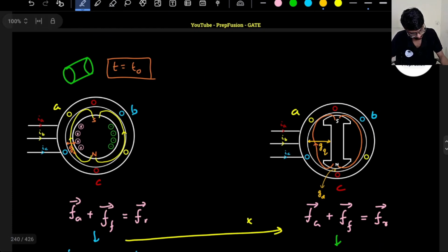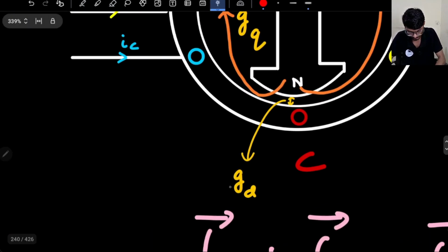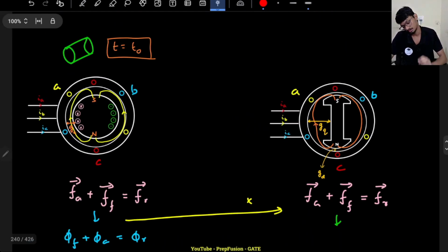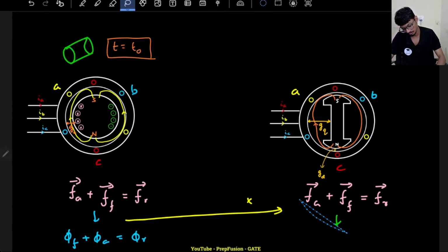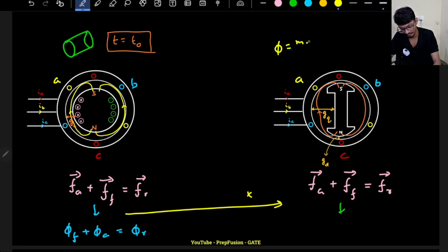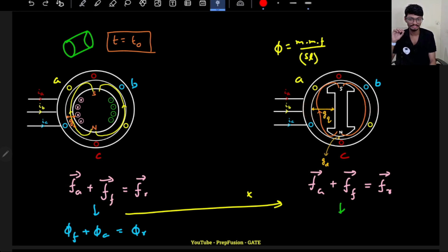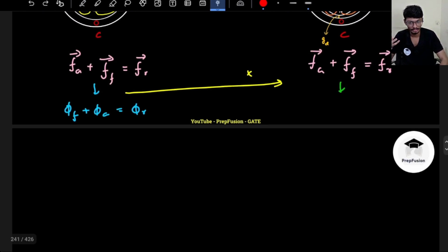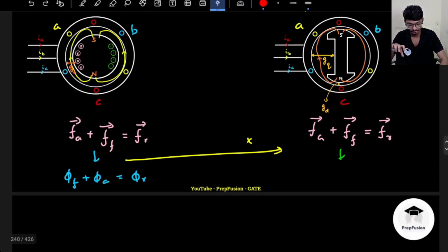Okay, so here the air gap will be very small, gd. Okay, so now I cannot simply, because flux is mmf upon reluctance. So if your reluctance is changing, so will your flux change, right? And your reluctance is changing depending on where I am at, right? So reluctance is position dependent. So reluctance is position or load dependent, right? Mainly it is position dependent and dependent on the load. Why is it dependent on the load?